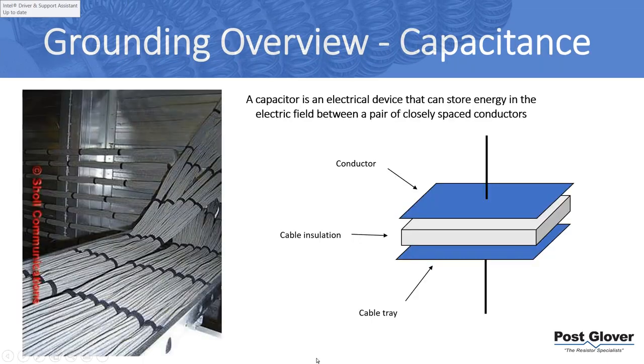Basically, a capacitor is two conductors with an insulator in between. So we're talking about a lot of different things: parallel cables, motor windings, almost everything in your system has a very small level of capacitance. And so it adds up to the system's capacitance. So that is a naturally occurring ground fault path. I call it leakage current, whatever you want to call it. The capacitive charging current is associated with that. And that's where you get the completion of the circuit.